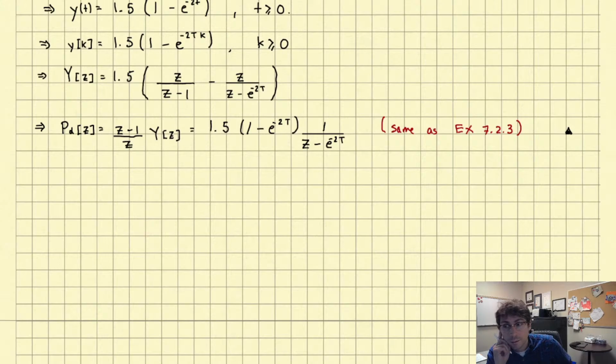Okay. Now, for first order systems, to do by hand, very simple, right? Whether you want to do it in the state space method or the Laplace method, either of them is quite easy to do by hand. As you get to bigger problems, or multi-input systems, the state space approach scales better and it's easier to do on a computer. Okay, so we've now basically finished our discussion on how you discretize a plant, how you compute the step invariant transformation.